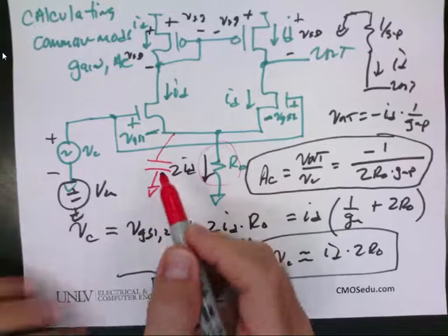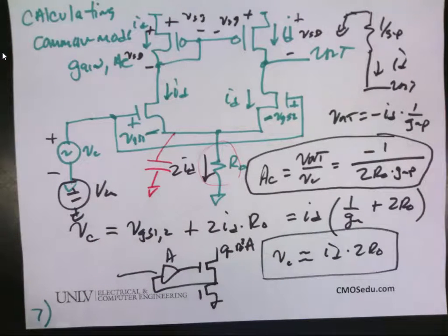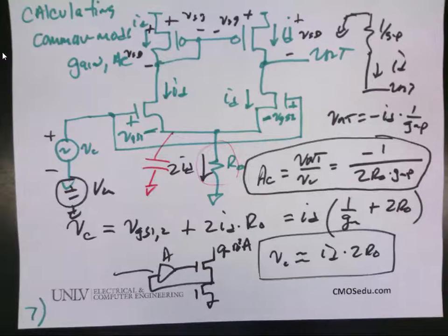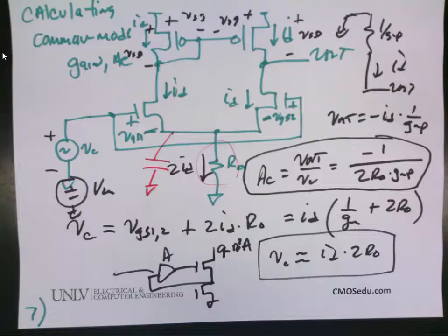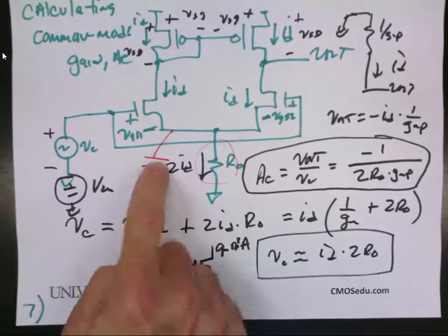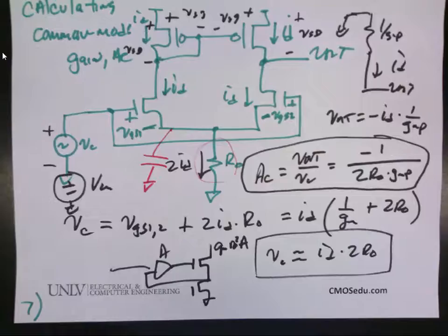So the common mode rejection ratio starts to fall off. What that means is I would like my common mode rejection ratio at a gigahertz to be high, because if I have any coupled noise from a microwave or whatever, it doesn't couple into my circuit and mess my circuits up and I start making bit errors or mistakes, okay? In reality, this capacitance will drastically lower the common mode rejection.